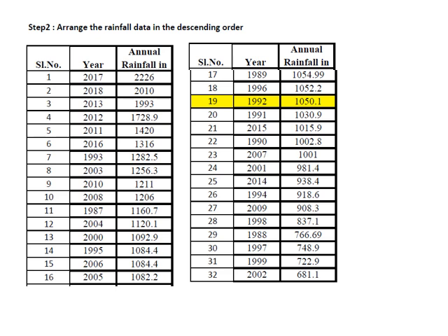The number of years of data collected is 32. So 60% of 32 comes to around 19. So serial number 19 is 1050. That means you have to design the bund for this particular rainfall. This dependable rainfall means a rainfall of 1050 that is coming for 60% of the years, that is, for 19 years out of 32 years. That is what it means.